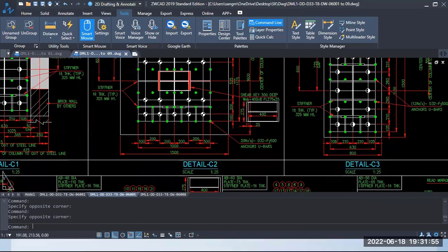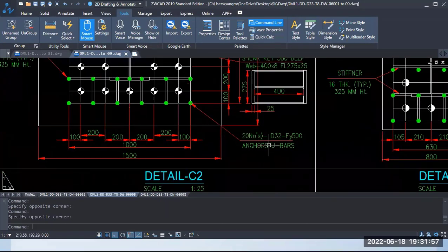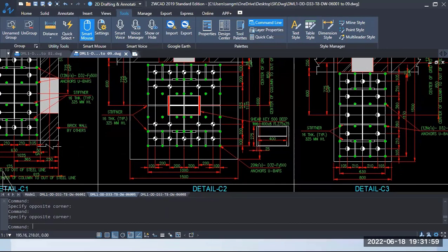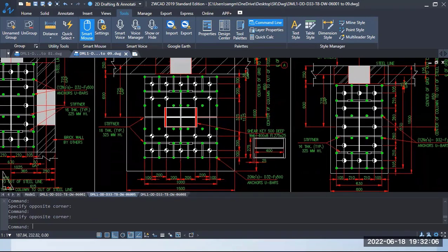The same additional reinforcement we have calculated and provided here, and that reinforcement also we have to calculate as per their methodology or procedures. As per Appendix D, ACI 318 we have to use it. That is the American code for concrete design, just like we have IS 456. We use ACI 318 for calculating the concrete capacity, and bolt capacity we can calculate based on AISC 360 or as per IS 800 2007.